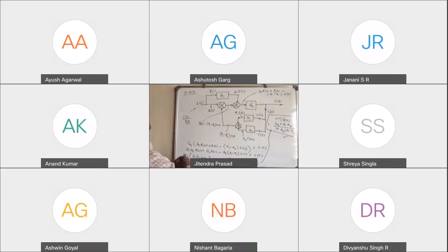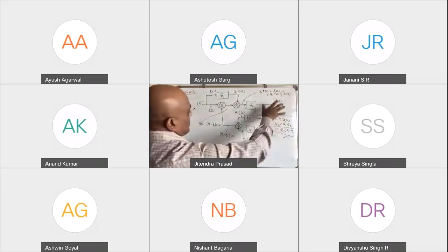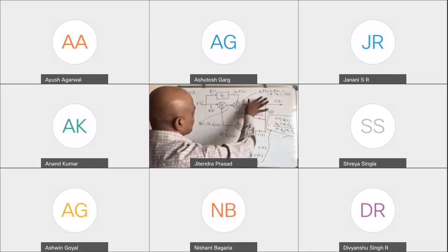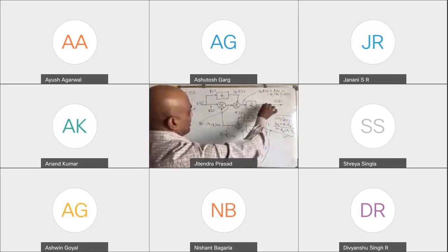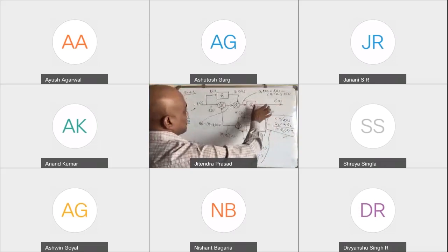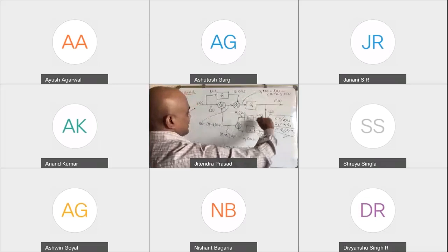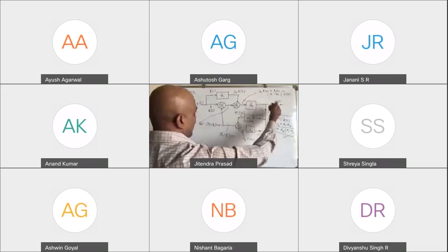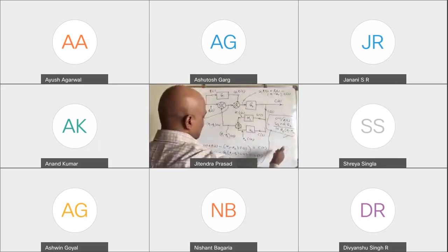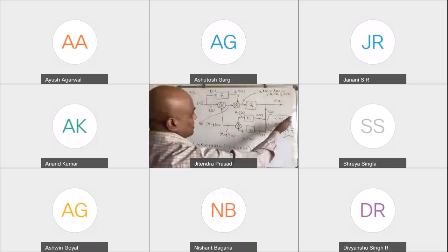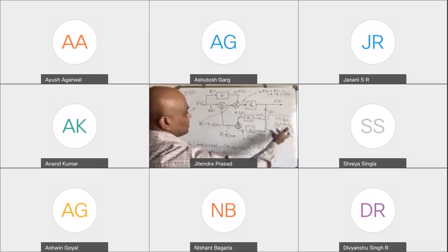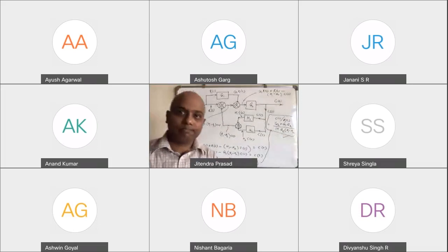So basically for you, RS is given, for you CS is given, and you are working backward from this side also, you are working forward this side also, so that finally you have to relate somewhere. Somewhere the CS and RS from this side and that side have to be matched. Here typically at the end, we will have both sides which have to be matched in values, and you solve them and you get CS over RS equal to this, and this is the closed loop transfer function. Clear?